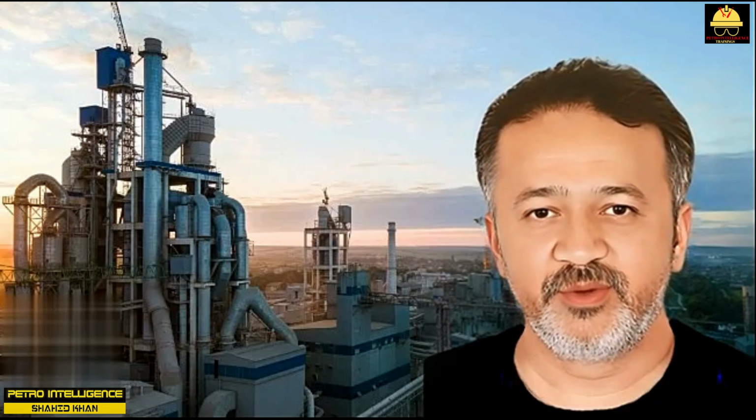I have worked in plants where I found 12-inch carbon steel piping, with piping velocities in corrosive services of 14 feet per second to cause erosive piping failures. For rich amine flow with particulate contamination, piping failures with velocities above 8 feet per second have occurred on units I've worked on. In summary, for services with moderate corrosion potential, I would keep tube side velocities below 12 feet per second, and perhaps a bit lower for U-tube type exchangers.